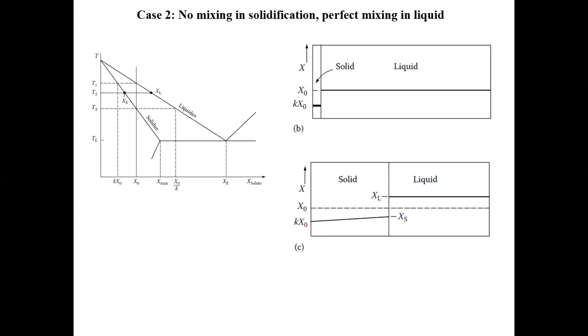Quickly in the sense that I don't wait until the solutes in the solid perfectly uniformly redistribute themselves, right? I don't wait for that because it's going to take too much time, but I still wait sufficiently long. So in the liquid, because diffusion is very fast, I still wait sufficiently long so that the composition in the liquid can still achieve whatever the equilibrium composition is. Okay, so it can achieve the kind of uniform distribution in the liquid, because as long as you repel a small amount of solutes in the liquid, you're going to quickly redistribute. So this is typically doable.